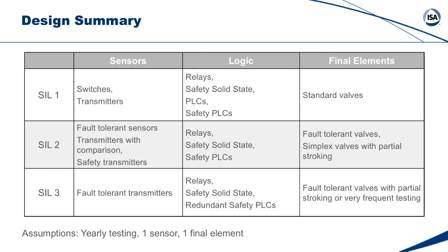You can have fault-tolerant sensors, 1 or 2 sensors. That's dramatically increasing your price, or cost, installed cost, and operating cost. General-purpose PLCs you can rule out. They're typically not going to meet it, your typical general-purpose PLC.